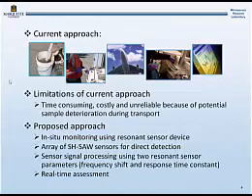And the way to deal with such leaks currently is depicted in these graphs here. So briefly, currently you still take samples on site, so you have to send personnel to the site. Then you pre-treat the samples, you transport them to an off-site laboratory, you analyze them, and finally you do data processing. But this approach regularly takes up to several weeks or even months. In addition, it can be unreliable because the sample can deteriorate during transport, and it is also costly and exposes personnel to potentially hazardous conditions. So there is a need to develop an on-site monitoring approach.